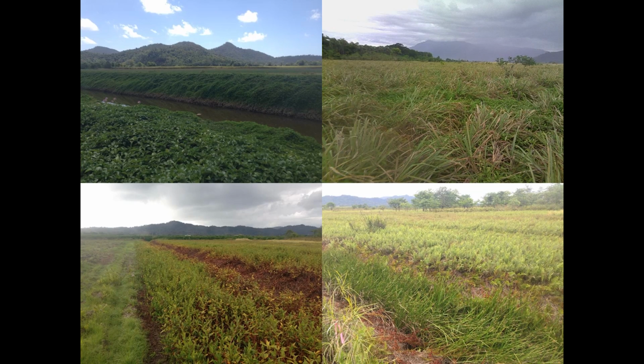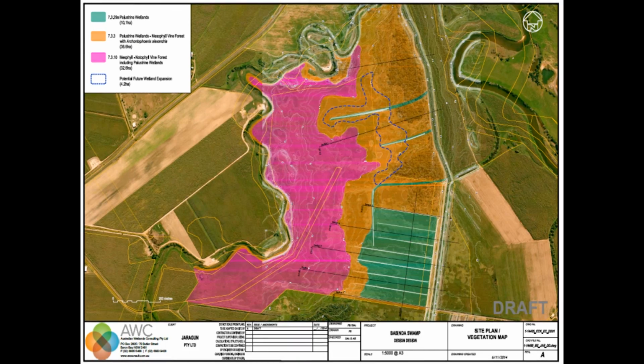And the reason it's like this is because he walked off farming cane 20 years ago and it's gone through that weediness stage, and I've done a few burns on it, and all of a sudden things are starting to come back. There's a lot of design challenges in what we're trying to recreate. Because we're trying to recreate nature, we can't necessarily put a marsh where it's not going to grow hydraulically. So we sectioned it off with LiDAR and said, well, this is where we're going to get our actual emergent macrophyte zone. So this is going to probably best emulate a treatment wetland.